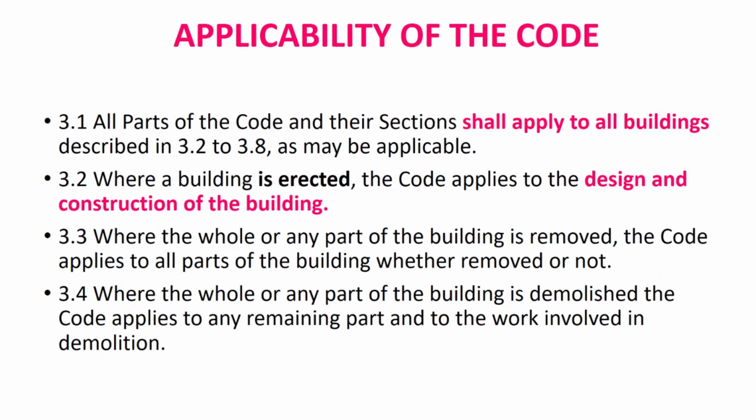Demolition of buildings, many times we don't pay attention to this important aspect. Please pay attention. Before a building is demolished, the owner shall notify all utilities having service connections within the building, such as water, electric, gas, sewer and other connections. Many times we tend to ignore or forget this, but please pay attention that these authorities, the utilities, those who are in charge of these utilities, should be informed in case you are going for demolition of a building.